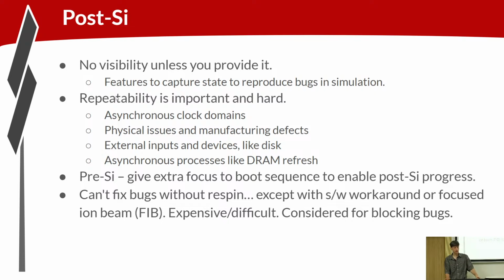First of all, your design is likely to have many different clocks. The clocks might be synchronous with each other or asynchronous. Where they're asynchronous, this is problematic for reproducibility. There's no way to reproduce exactly the same behavior if the clocks are not forced into alignment.